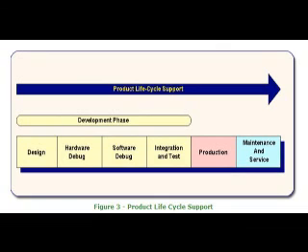When the prototype arrives, a test fixture for the IC is not available and, therefore, manufacturing defects cannot be easily detected and isolated. Small size products do not have test points, making it difficult or impossible to probe suspected nodes. Many complex programmable logic devices, CPLDs, and flash memory devices in PGA packages are not socketed and are soldered directly to the board.